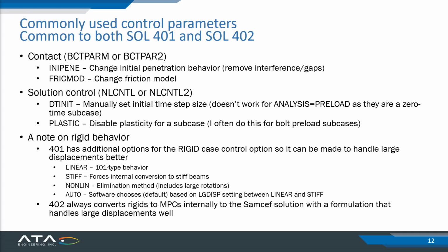Then there's the plastic parameter, where you can enable or disable plasticity individually for a subcase, which I will often find myself disabling plasticity for bolt preload subcases, for example.